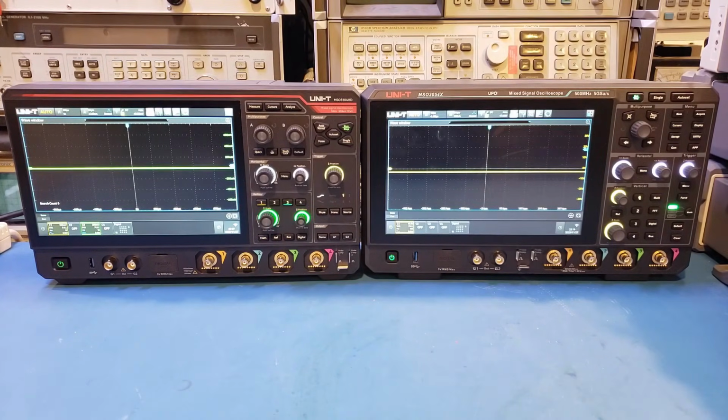Anyway, so what are some of the main advantages of a 12-bit scope as compared to an 8-bit one? While I still have the MSO3054X up here, let me actually show you that. The most obvious answer is that we now have more vertical resolution. Instead of representing the signal in 8 bits or 256 levels, now we have 4096 levels, so obviously you have more granularity.